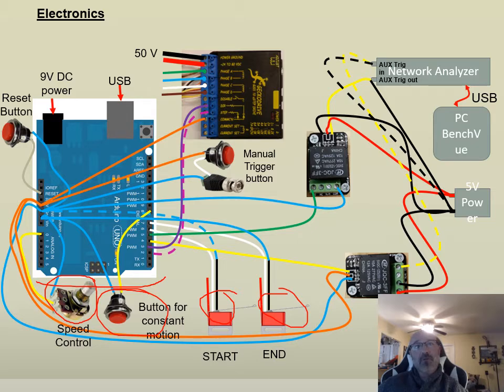So the first way to do this, what we did was a manual trigger button. So we're kind of moving away from an open loop system into slightly more of a closed loop system, where now it's going to be based upon us pushing this button. Every time we click our trigger button on this, it's going to move and advance the cart a set pre-programmed distance, stop it there, at which point we can send off the signal from our network analyzer into this, wait for a receive signal, we receive it in the network analyzer, goes into our data acquisition system. Okay, we see it, it's done.